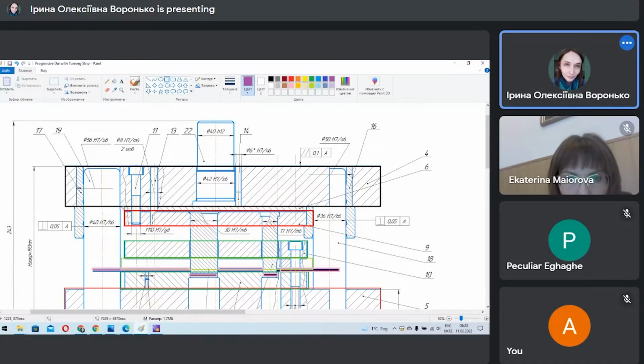This protective plate saves our upper plate each time when we cut the strip, because each time we use some big force for cutting material and push on our upper plate. To protect our upper plate from destruction, we use a very thin but high-property, very hard steel plate in this place.